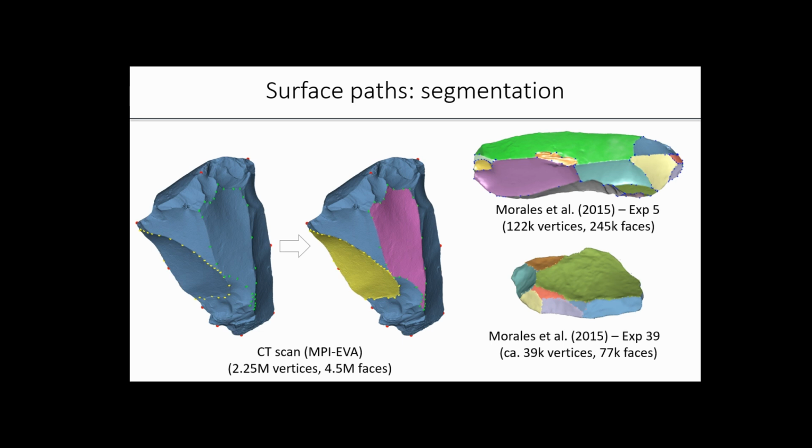There are a couple of gotchas. If you have meshes that have been simplified, and in flat areas you have very large triangles, whereas on ridges you have very small triangles, it doesn't work all that well. So you need to remesh it to a uniform size.